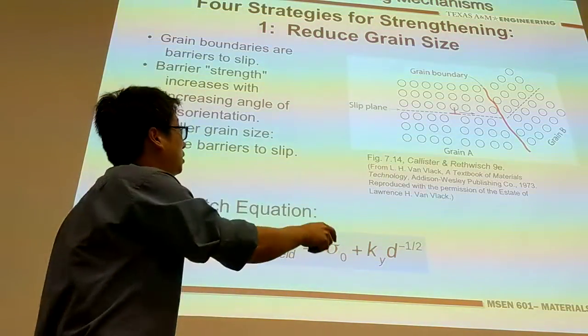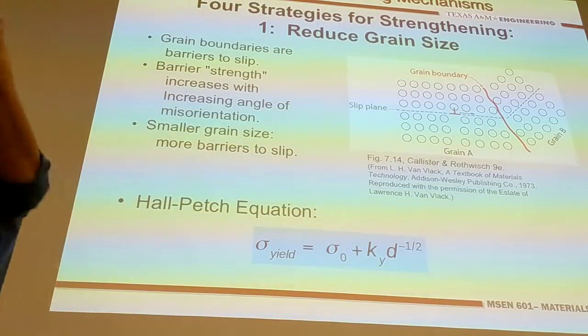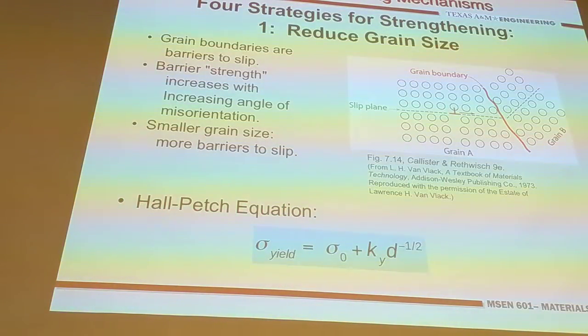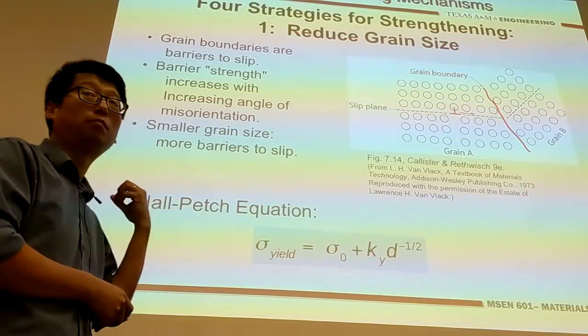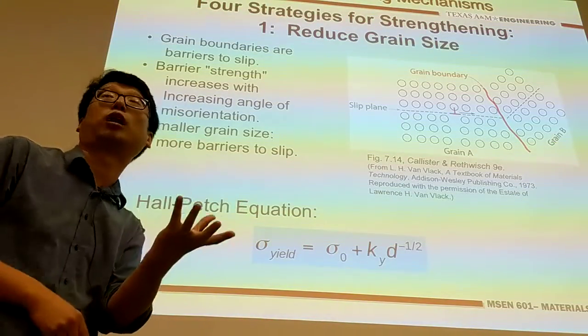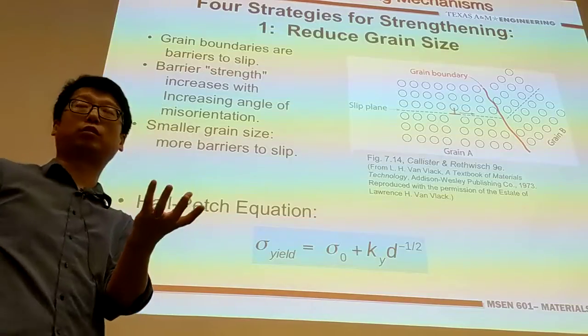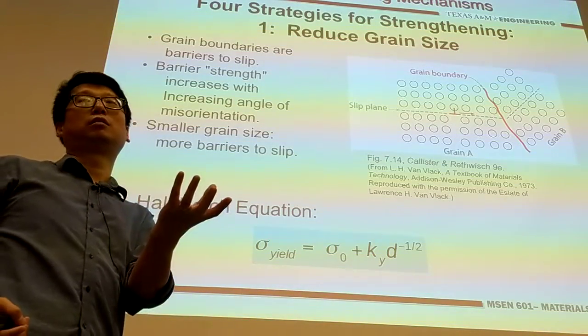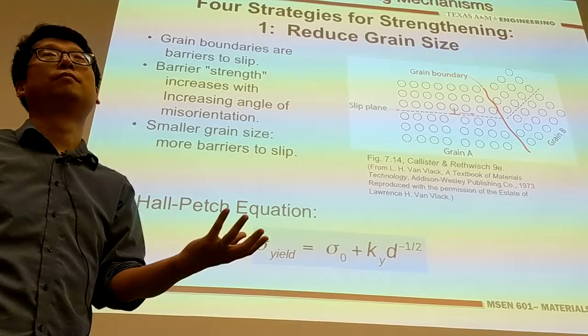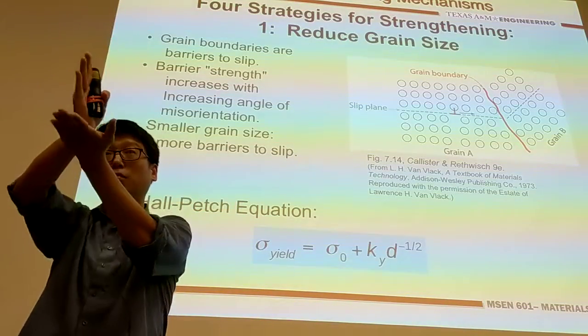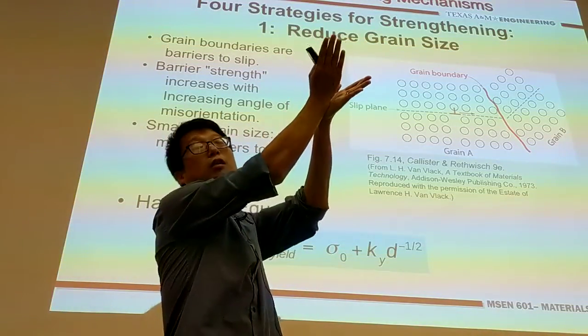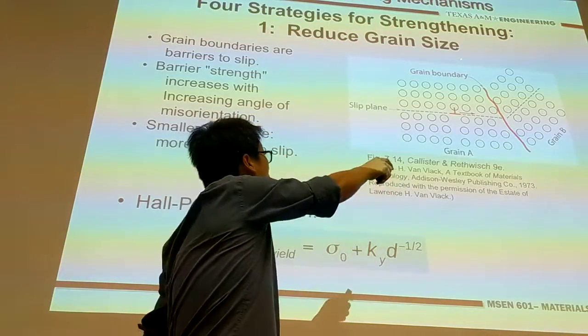So therefore, through this mechanism, you're basically saying, I want to create a barrier for dislocation moving across the grain boundaries between many, many grains. Even though dislocation can be generated and can propagate inside the grain, when they try to move across different grains, they have a hard time, because the dislocation, the half atomic plane, needs to rotate direction and go to another crystal. They need to overcome this barrier.